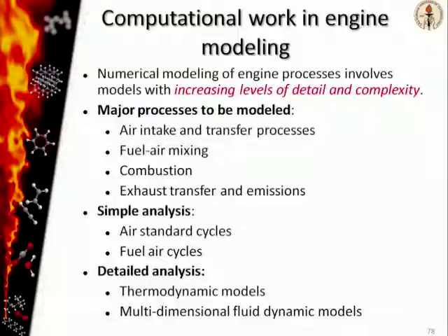The simplest analysis consists of what we saw a few slides before, where you take just the cycle and do a first law thermodynamic analysis, and then you get some expression for thermodynamic efficiency and work power output from the engine. Then you can do a more detailed analysis where you actually include thermodynamic models or multidimensional fluid dynamic models in order to simulate the engine cycle.